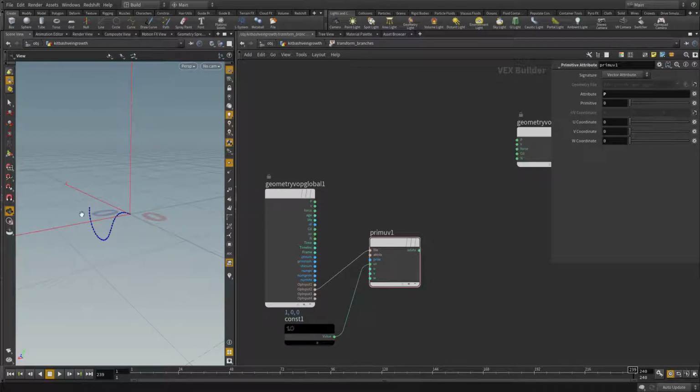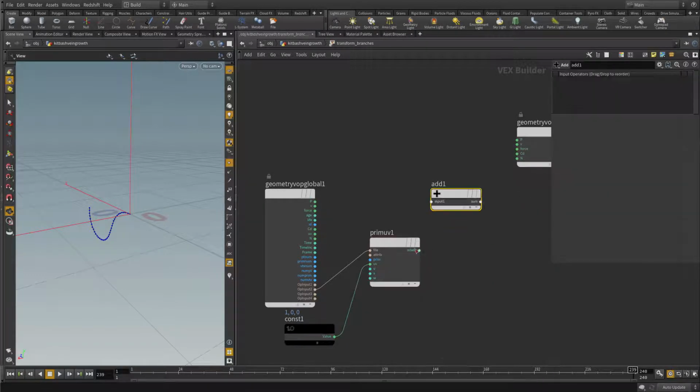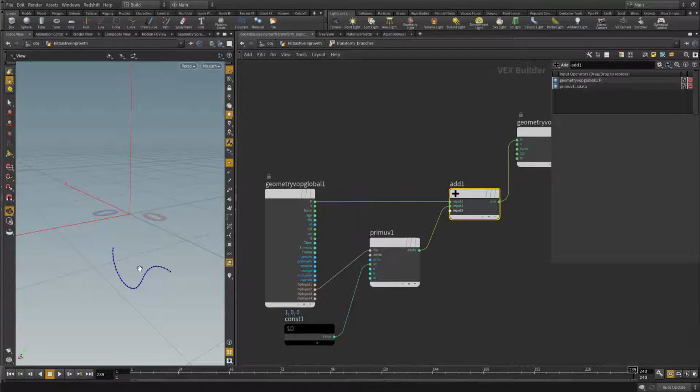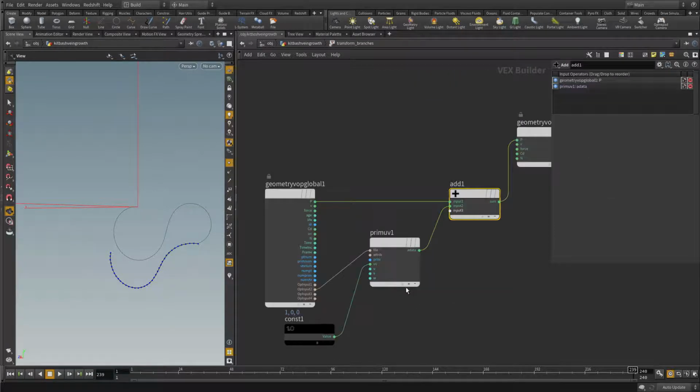And to move this geometry to the end of the other one, we just add this position to the position of all the points, like so. If we do that, this one jumps over. If we go up one level and make the other one visible by templating it, you see that the geometry jumped to the very last point of our second primitive. That is good. But it does not stop here.